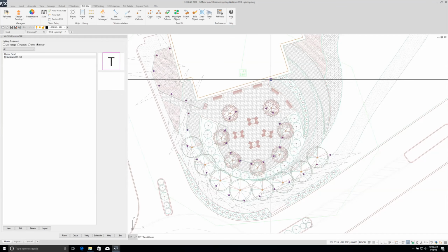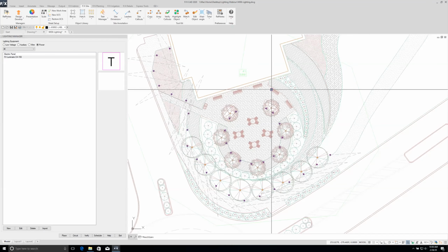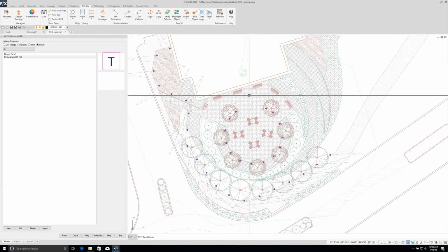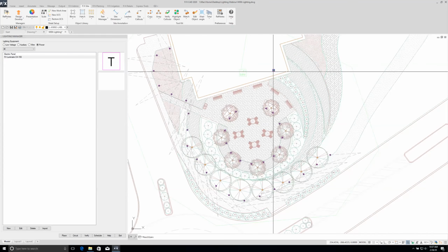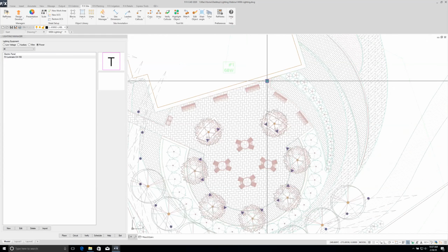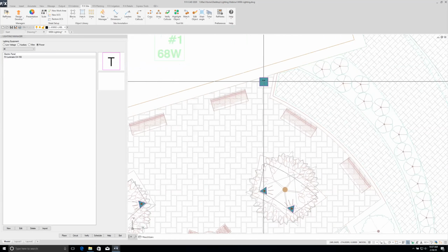And I'm going to basically want to place this because I'm not going to daisy chain all of these together. I know I'm going to be creating a couple of lighting runs between the fixtures. I want to place this somewhere strategically so that it's somewhat centralized with the lighting fixtures and also on a wall. So I'm just going to place this over here.